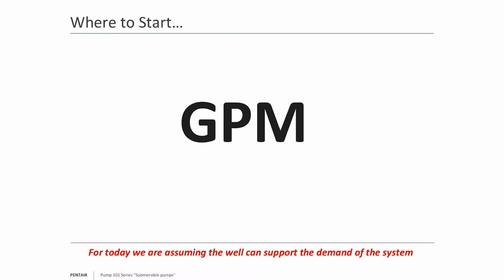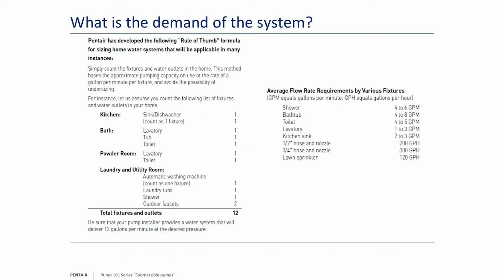And we're going to be talking residential homes here. Larger projects are often very specific, and I'll explain that. Now, one of the things I want to mention is that when you talk about residential homes, there is no bulletproof formula to do so. A lot of times it's going to be dictated by the capacity of the well. If the well can only give you 7 gallons per minute, you will not put a bigger pump in than 7 gallons per minute, probably. You'll probably run 5 gallons per minute. And the homeowner will have to learn to budget their water flow.